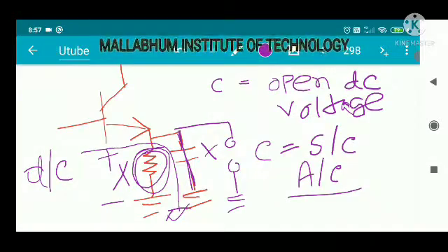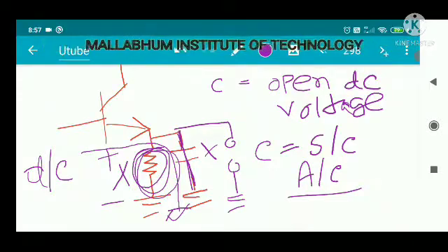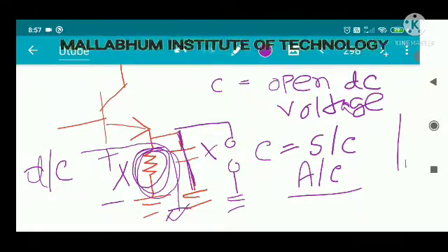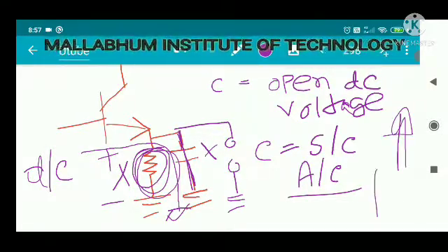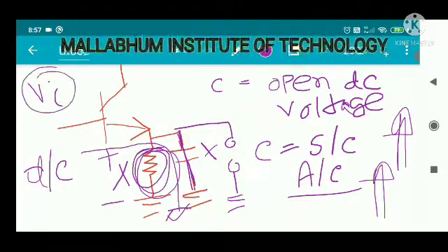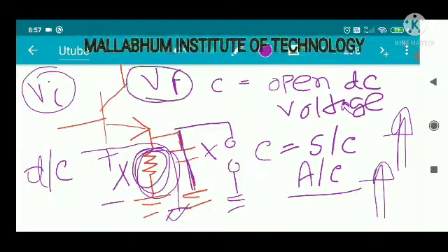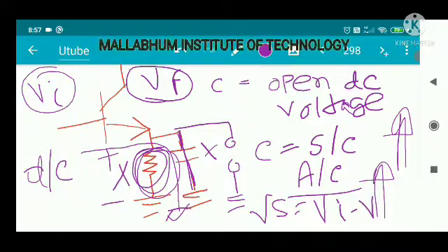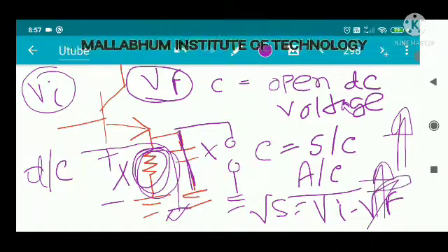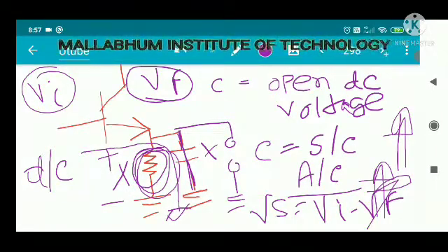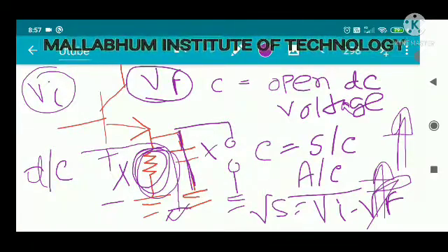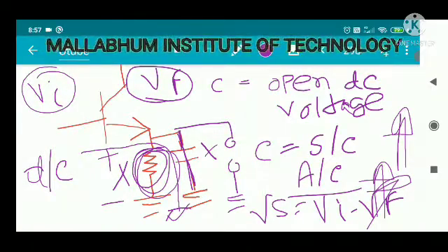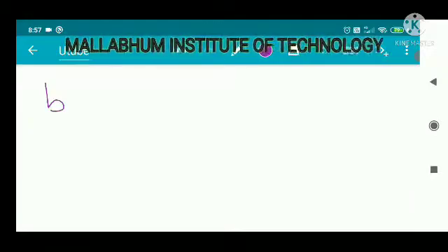So just by applying a capacitor across the emitter resistance, we are improving the DC stability as well as improving the AC analysis condition. That means your input voltage will not be reduced by the amount of the feedback voltage. This Vf is eliminated in the AC analysis, but it is still present during the DC analysis.